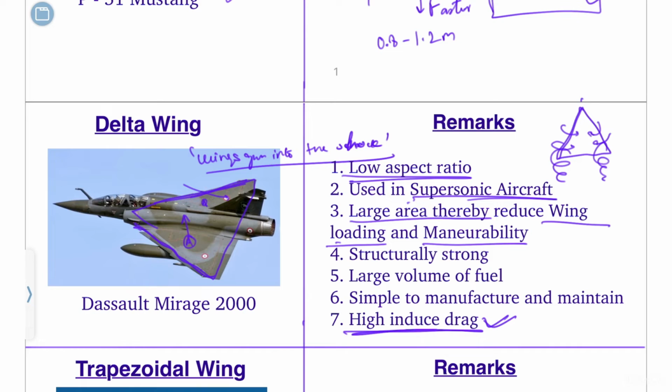Okay, so lift is equal to weight is equal to half rho v square S CL. If we divide weight by S, which is equal to half rho v square CL, this is known as wing loading, which is the weight per unit surface area. So the surface area is too high, so wing loading is reduced. Per unit surface area, how much lift is generated, or for a particular area, how much weight it is carrying to generate the lift.